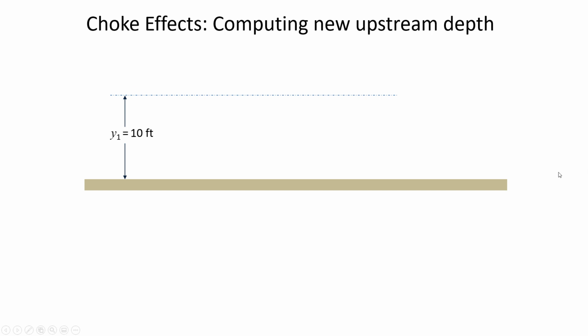Let's say that we have water flowing with steady, uniform flow. If conditions are steady and uniform, what equation do you use to find the flow depth? We don't have to use the specific energy analysis. We can use something else if conditions are steady and uniform. It's named after a person. A lot of equations named after people. Not a lot of open channel flow equations that we've learned this semester. You find the flow depth with what? Manning's equation. That's right.